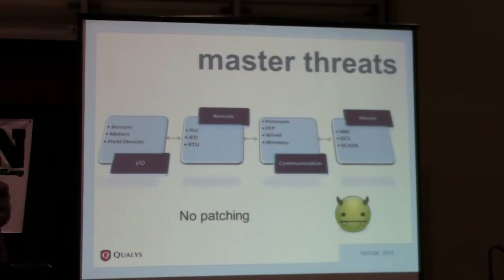No, my SCADA vendor doesn't tell me if the patch is safe or not. So I don't want to break anything. I don't want my patch to break or stop some conveyor belt or something. So I won't apply that patch. And that basically leads to these systems being unpatched and open to all viruses and worms and all sorts of malware which could have been stopped if they were just patched. But there is actually no good answer here, and we'll look in a moment at how to secure them, on what could be done.